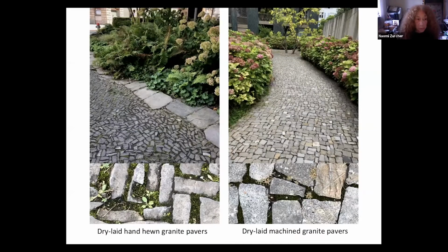Dry laid pavers, the best for tree and soil, are set on a bed of tamped down sand with mason sand between the joints, requiring minimal substrate compaction. The sand acts as a cushion, which accommodates substrate irregularities and affords the uncompacted soil beneath the sand access to gas exchange and water infiltration.